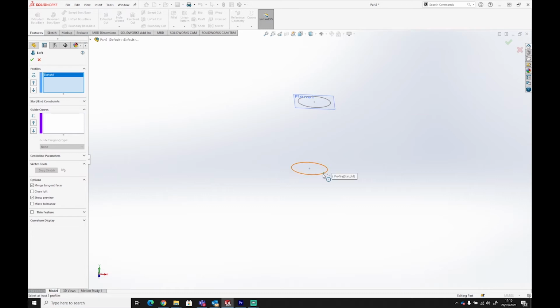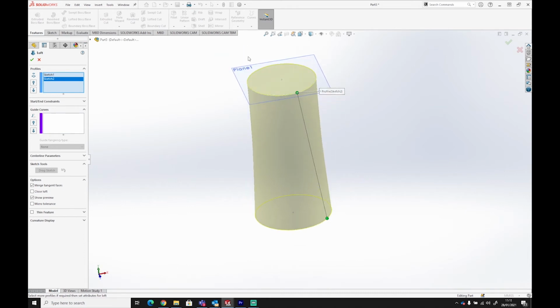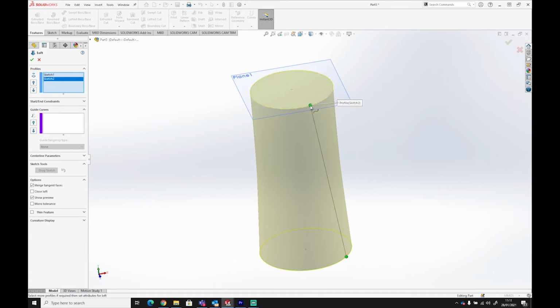If I click the bottom one and the top one, like so, it's going to give me a projection from the base up to the top, like so. As you can see, it narrows out on each other. Now, what we can do is manipulate this. Let's zoom in a little bit. We can manipulate this so that with our profile line coming down the side, I can turn that around and it will thin it out in the middle because it'll twist the shape. Okay, and the more I turn it, the thinner it'll get in the middle, creating some sort of hourglass shape.